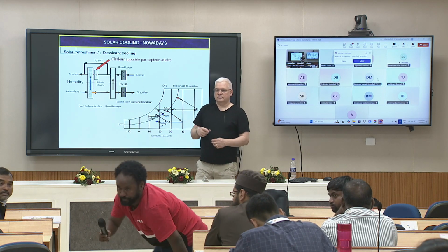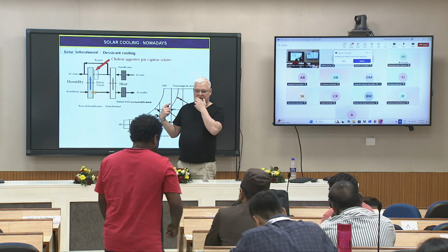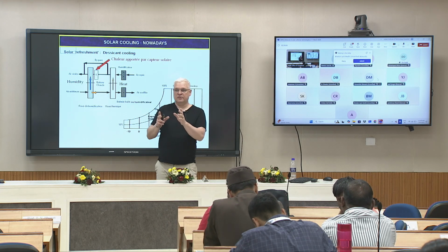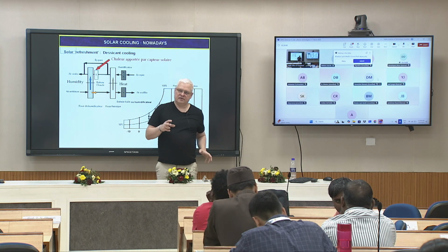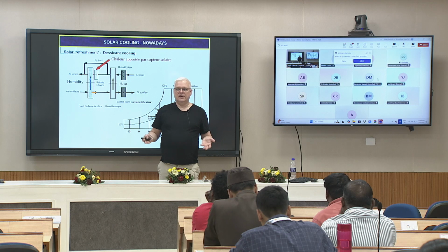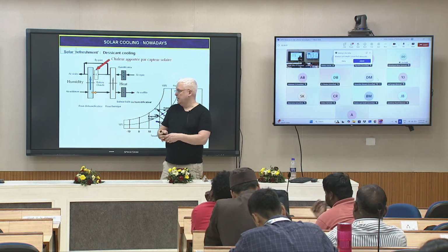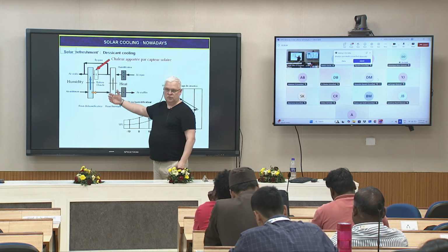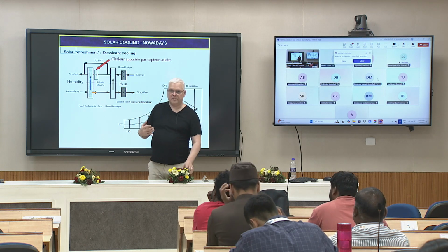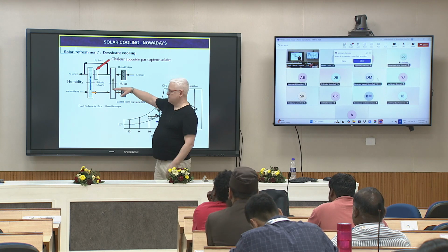Yes, it is a double flux system that is now compulsory in new buildings in Europe. This system is double flux, so you are mastering the inlet and you are mastering the outlet, because the buildings are fully tight and very well insulated. This heat exchanger during winter time allows you to recover a part of the heat which is rejected outside. During winter, it's also operated.